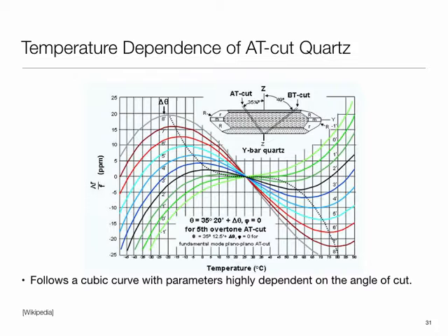You have 4 parameters to learn for a cubic curve, so a small number of measurements can take care of it. So in theory, we can do all of this. The act of calibrating takes time, and that's why temperature compensated crystal oscillators tend to be very costly.